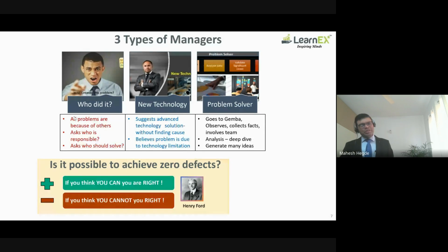He took that project, and then we applied the tool called paired comparison. This is based on Tukey's test. It is a part of Dorian Shainin's methodology, but we don't use the Shainin methodology. We use good-bad analysis, Tukey's test. There's a book by Keki Bhote on world-class manufacturing from that. So I told him, collect 8 best tires and 8 worst tires, measure suspected parameters and send me. After a month, he measured and sent me the data for 84 suspected parameters. Best means didn't fail. Worst means failed within 3 months, early failure. With a lot of difficulty they measured this and sent it. I did the analysis.